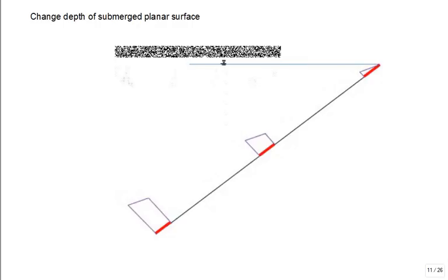Here's a question. I have the surface way up at the top. If that edge is at the top, it's not submerged, then I really have a triangular distributed load. And I try to put the half mark and the 1/3 mark. Where is the resultant force applied for that first top case? It's right at that 1/3 mark, true? But I go down some distance. I look at it. You know what? It's still a rectangular load and a triangular load on top. I think about the 1/2 mark and the 1/3 mark. Where is the resultant force placed for this system?